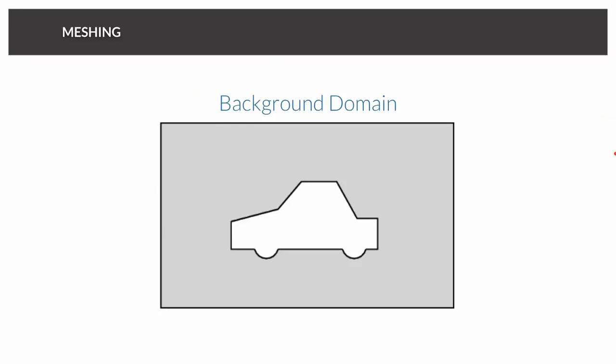And meshing actually is the biggest bottleneck in CFD. Usually it takes like 70% of your time. SimScale is using a toolbox called OpenFOAM in the background for meshing and CFD calculations. And OpenFOAM is also used in F1 by several teams. I'm quite sure they modify it, but the great thing about OpenFOAM and SnappyHexMesh is that it has a completely different approach to meshing.